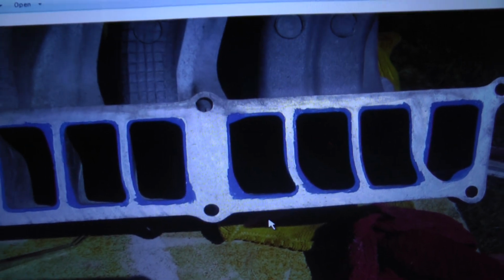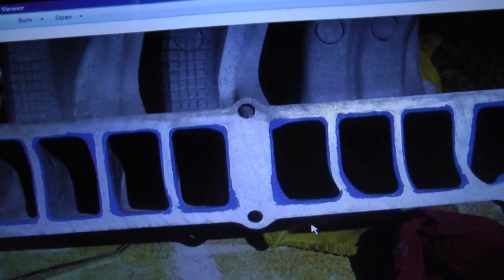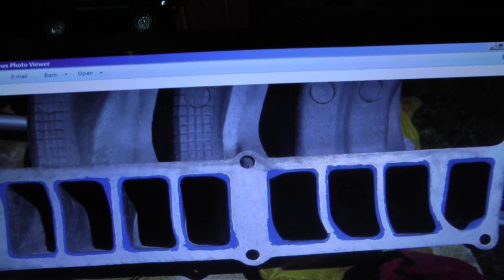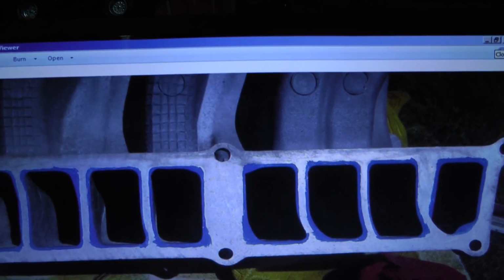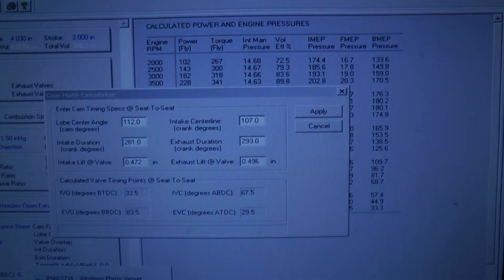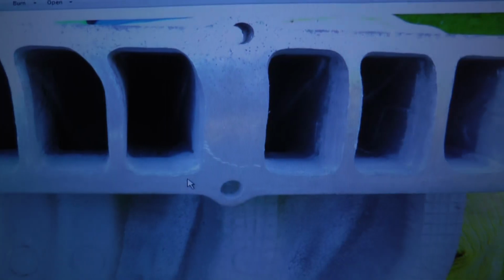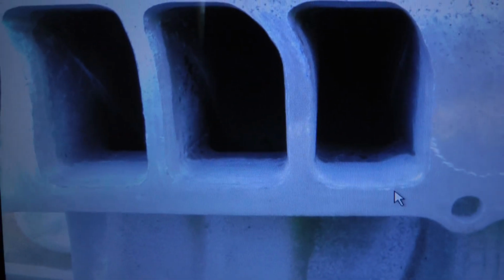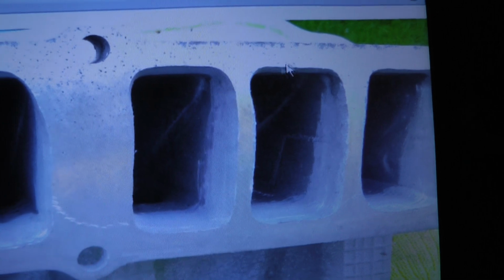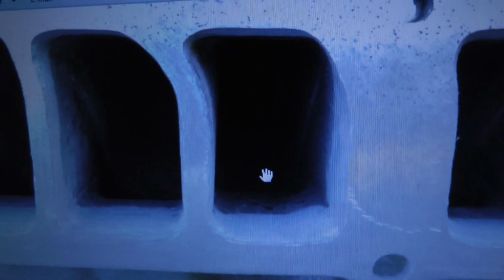I think this may change the profile because it's a low-end torque. I was hoping this would open up the mid to higher range, because my intake manifold ports are ported and the heads will be a little bit opened up. So you can see that here. Now you can see how much they opened up. Originally I had a cool photo of just opening the port. Here you can still see a line that wasn't blended yet, and you could see how many millimeters were open before blending it.